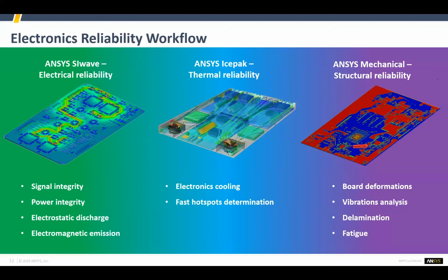But then we can also do mechanical and structural reliability, possibly vibration analysis. We could see if a component gets really warm, how it deforms, and then how that deformation of your antenna affects the far field as well as the near field performance, and of course the return loss and insertion loss performance, the S parameters as well. So not only do we allow our customers to design small antennas with HFSS, we can mount them on large structures, and we can also help our customers determine the thermal integrity or the mechanical integrity or the electrical reliability of their product.